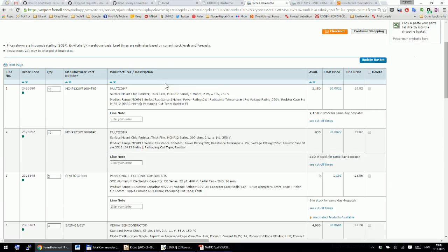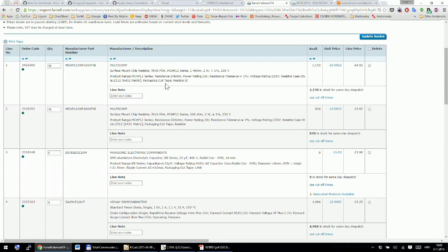So every time I make my own PCB, each time I check the footprints, and I rarely use a footprint that I didn't check, I just placed it on board or whatever. So for every footprint I make, I download data sheets from the maker, and I try to make my own footprint if there's none in the program that I use.